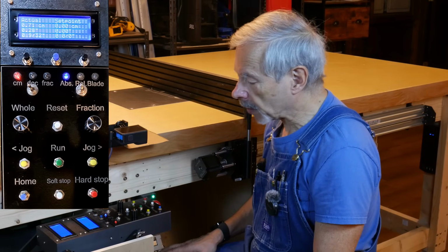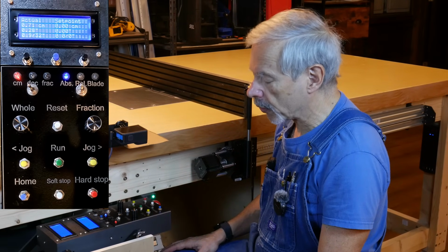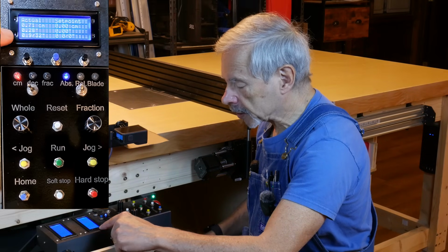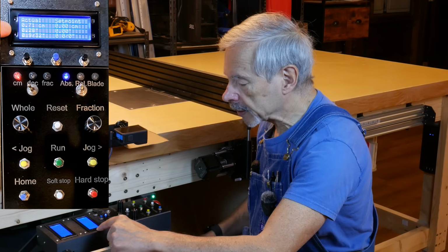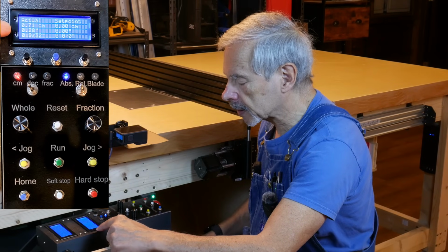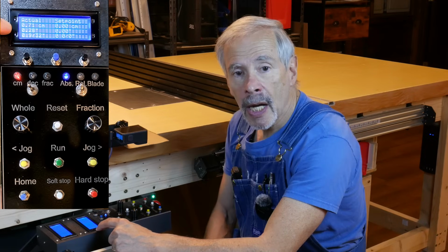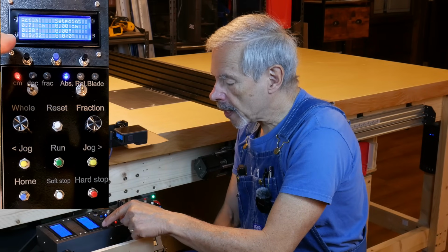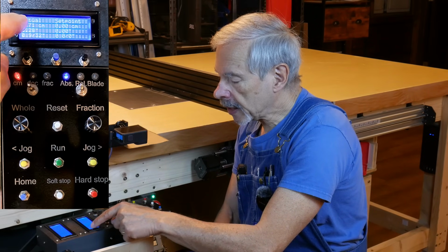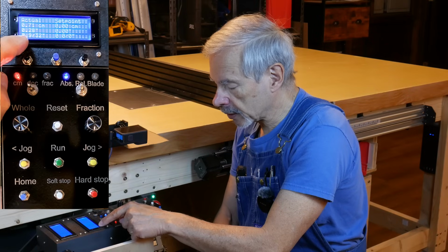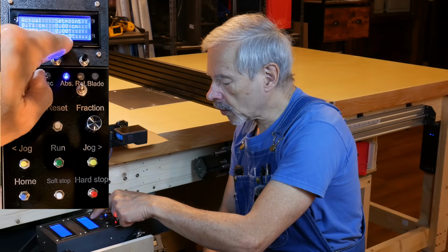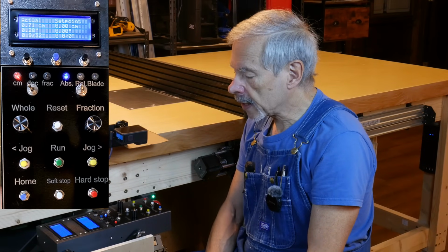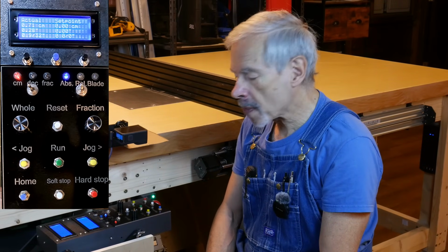The main points about this user interface that I have to go through before I can show you an actual demo are the 2 displays, of which we are really using only the lower display. So this is the only display of interest to us. On this display there are 2 columns, the left and the right column. In the left column we see the actual position of the fence relative to the blade, and in the right column we see the set point. That is the position of the fence that we would like to have.